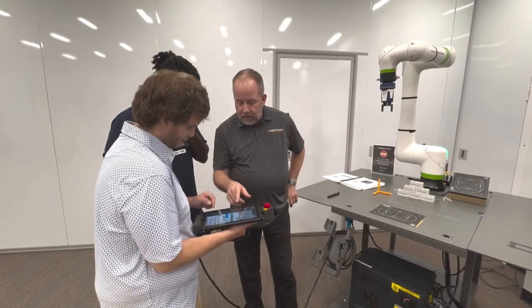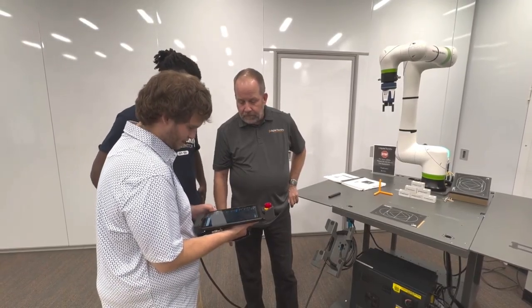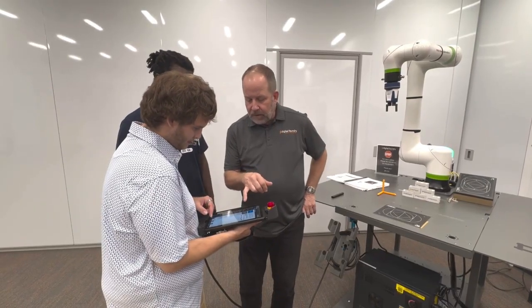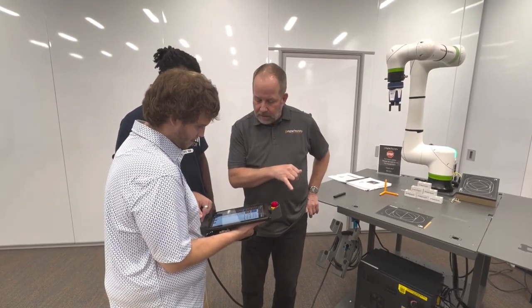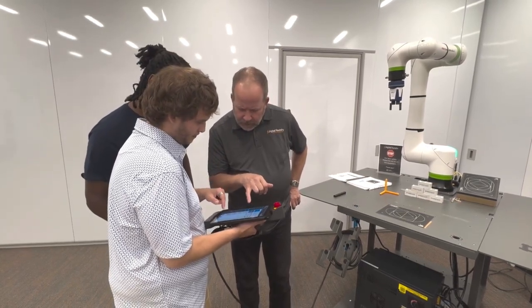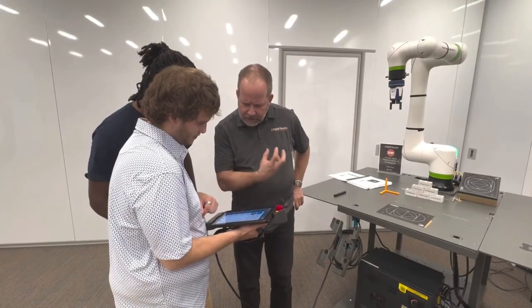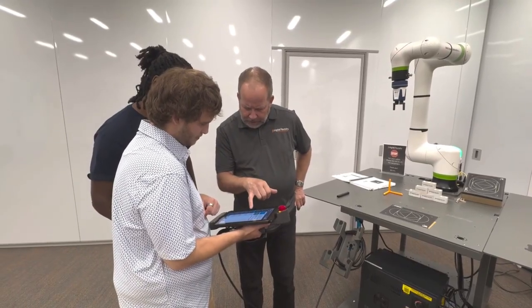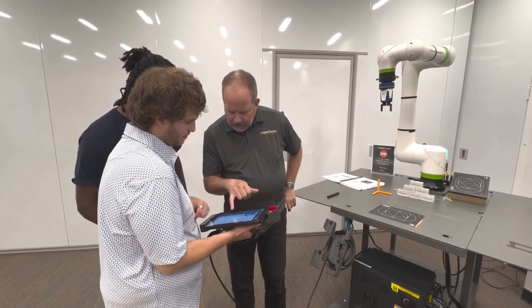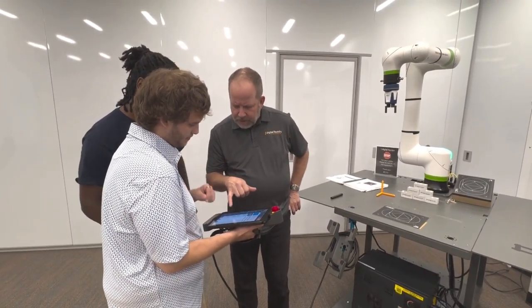Go look at uTool payload setup. This allows you to program in the specific payload that you want the robot to handle. Entering the schedule number, so you have to set up a schedule for each payload, the payload mass, there are a couple of those there, measurement at position, and so on.